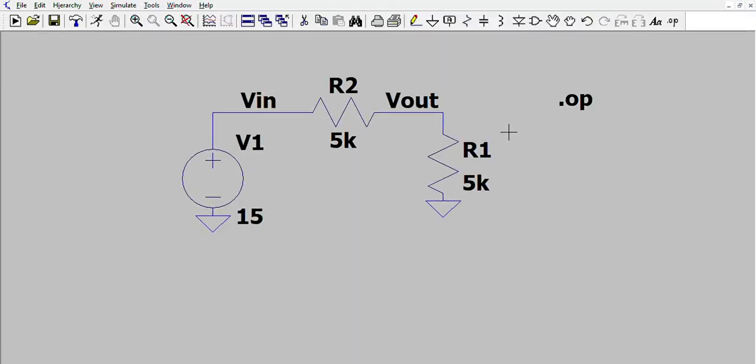For the DC sweep simulation, I will change the circuit a little bit, like you did in the 5th week lab. I will put a diode, and we will sweep the input voltage source like you did in the 5th week. Right click on the resistor, and let's change the resistance value to 1k like we did previously, and I press delete and delete the second resistor. Instead of the second resistor, I select the diode, press Ctrl with R, and put the diode.